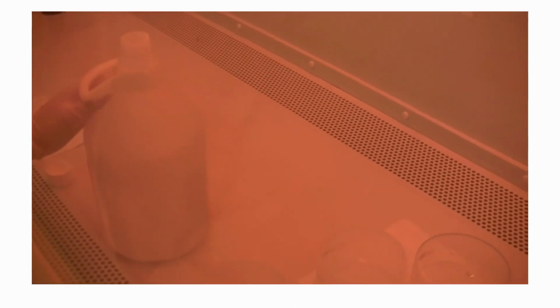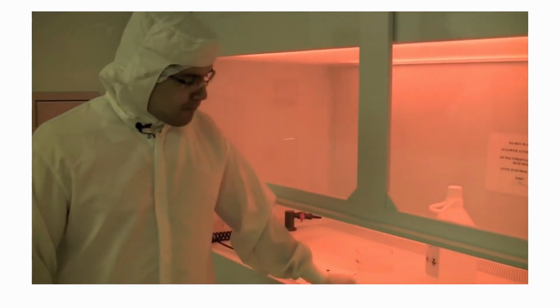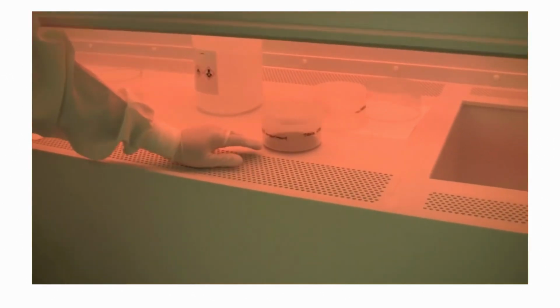Typically, you only need enough SU8 developer to cover the sample. So I'm going to bring over a sample very quickly. I'll just pop it in. Next, I'm going to pour very carefully, just a little bit. You don't need a lot. That's all you need. Now, SU8 develops faster if you agitate it or if you use an ultrasound machine. The INF provides an ultrasound machine that you can borrow. Typically, this can take anywhere from 1 minute to 20 minutes. It really depends on how thick your SU8 layer is. For thicker layers, more development time is needed. But most importantly, I want to stress, you don't need that much developer. Any more than this is wasteful. As you can see, it just only covers.